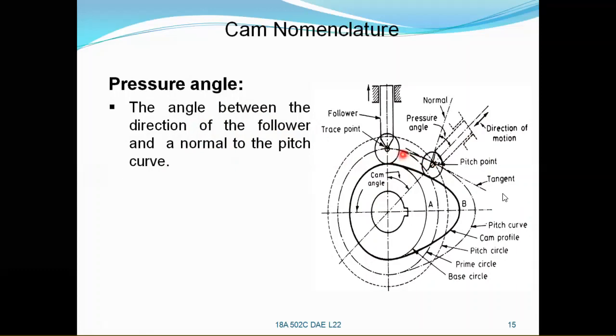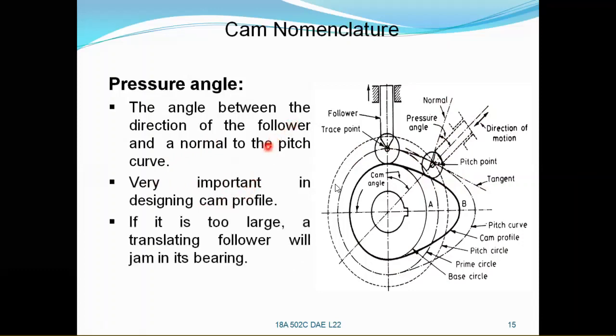If you draw a tangent to this pitch curve, this will be the normal to the pitch curve, and the angle between the direction of the follower and this normal is called the pressure angle. And it is very important in designing the cam profile. If it is too large, a translating follower will jam in its bearing.